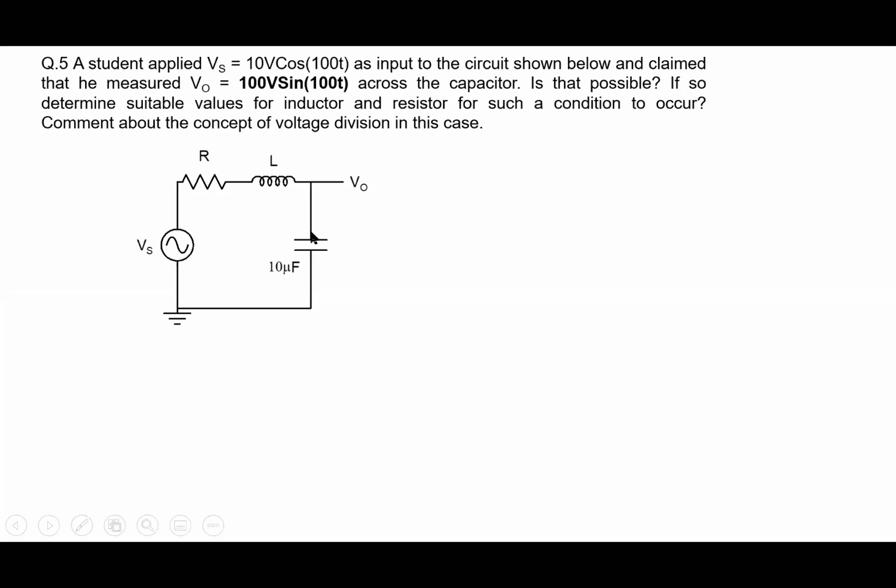It's because normally when we handle resistive circuits, we know that you have a supply voltage and then there would be a drop across various elements. And therefore, any voltage across any element is less than the supply voltage. So when we handle resistive cases, that's the notion that we carry, that voltage across any element would be less than the supply voltage. But when you come to these AC circuits with these impedances, interesting things happen and that rule is no longer valid. The expectation that the voltage will always be less than the supply voltage is not really true, but it's a useful result. So let's look at it.